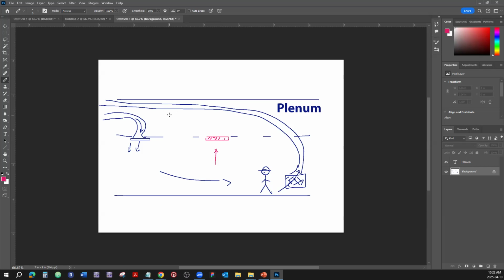So somewhere in the ceiling space, there is going to be a huge cavity, and that will be the cold air return to the furnace, and that is going to have air ducts. And this is how the air gets from this room. So this is going to create a negative air pressure, so suction begins, and it's going to create enough negative pressure so the air from this room is just going to be sucked in through that grid, through the plenum, and it's going to make its way somewhere to that cavity that is there.